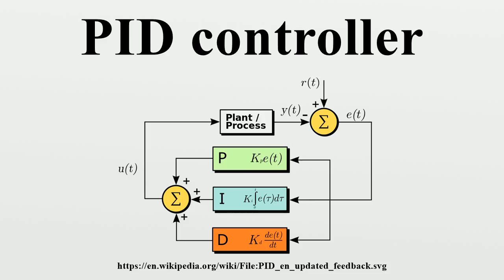Optimum behavior. The optimum behavior on a process change or setpoint change varies depending on the application. Two basic requirements are regulation and command tracking. These refer to how well the controlled variable tracks the desired value. Specific criteria for command tracking include rise time and settling time. Some processes must not allow an overshoot of the process variable beyond the set point if, for example, this would be unsafe. Other processes must minimize the energy expended in reaching a new set point.